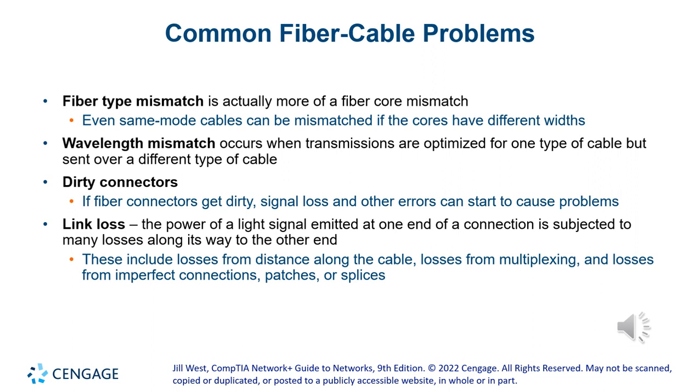Dirty connector is very common. With time, there's always an air gap between the connections on either end of the fiber at the patch panel or the piece of equipment. So with time, little particles of dust can get in there, and it will cause problems. It's not something that you need to clean every month or every other month.